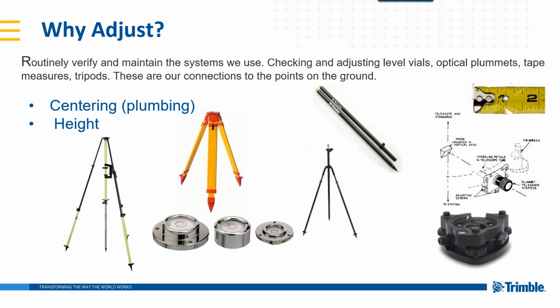One is the instrument's own built-in error. It can only measure up to a certain degree of precision. We need to take care of our equipment. We need to make sure our optical plumbs are calibrated properly, and our horizontal and circular bubbles are properly maintained and cleaned. The points on the tripod that we use to plumb over need to be proper too; those can wear out over time.